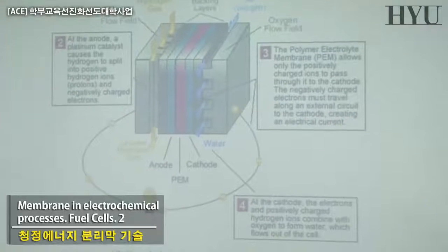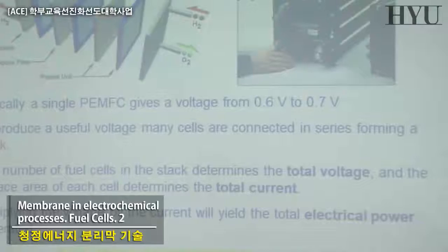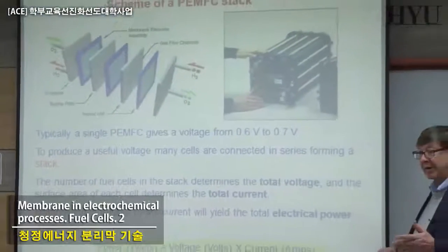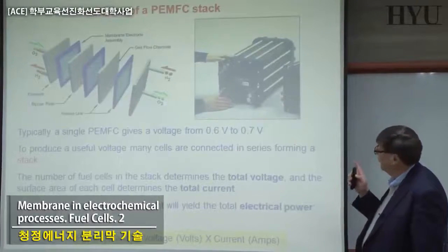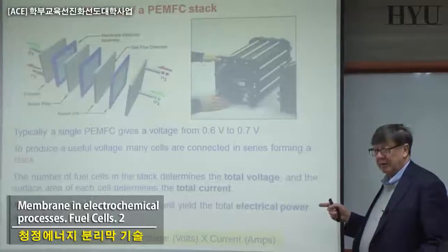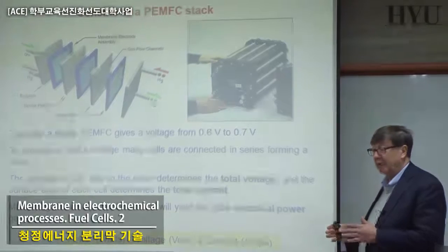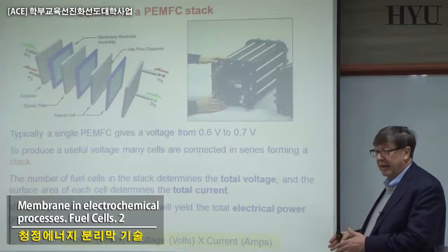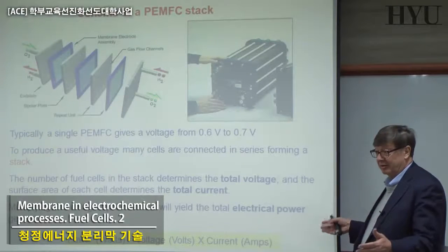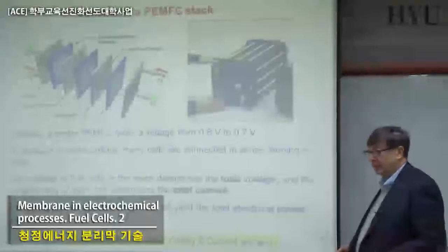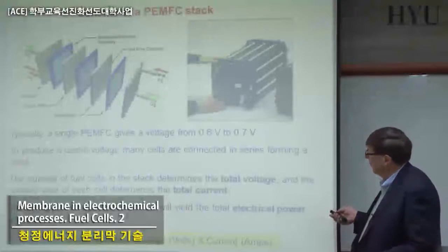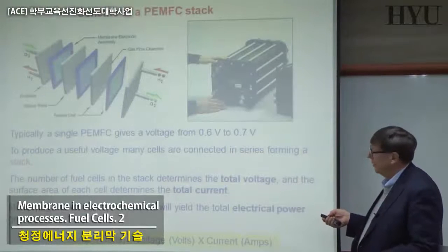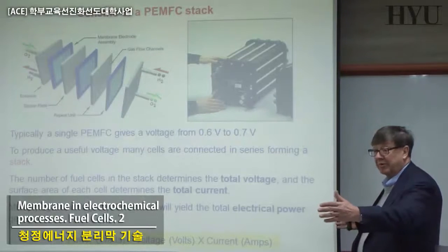Now if you are working on this, you will see the system is a little bit more complicated than expected. It's not just a membrane, etc. You can see here a single stack; keep in mind that any fuel cell is normally a set of these units. These normally are 10, 20, hundreds. The overall potential voltage you can obtain in the system is related to the one of the single cell multiplied by the number of cells.